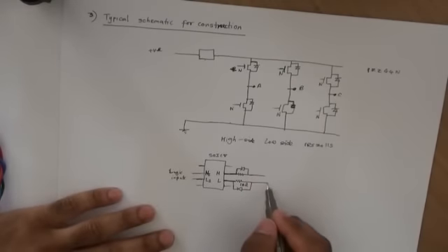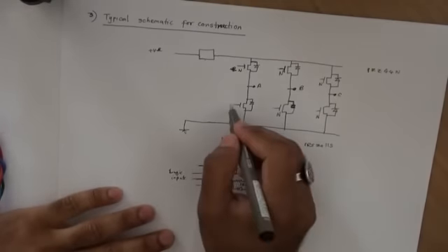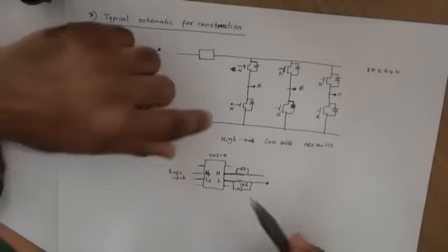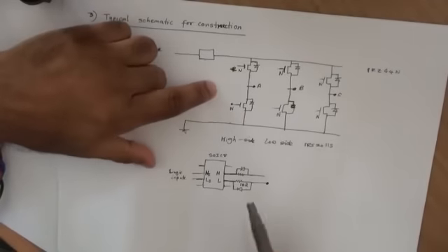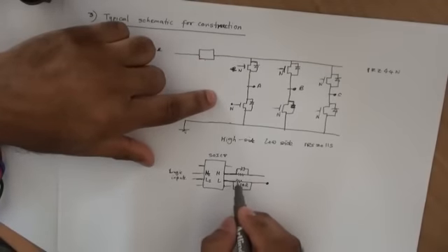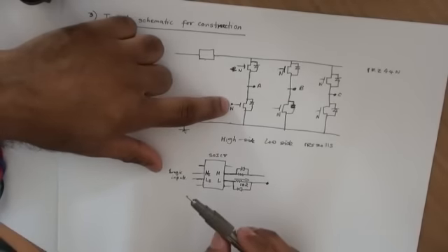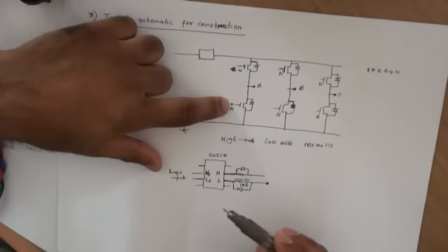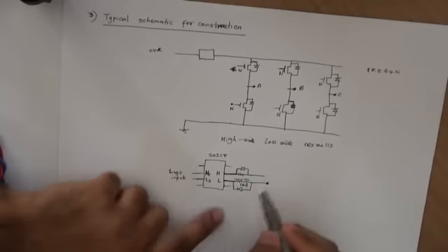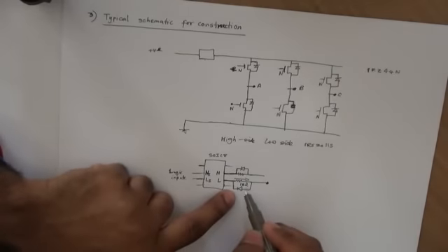So let's say we had this one hooked up to here. When you're turning the MOSFET on, it's all fine and dandy. You have electrical charge going through there, and it's turning it on. But when you're turning it off, you really want to turn the MOSFET off as soon as you can. And to do that, that's when you're using this diode.